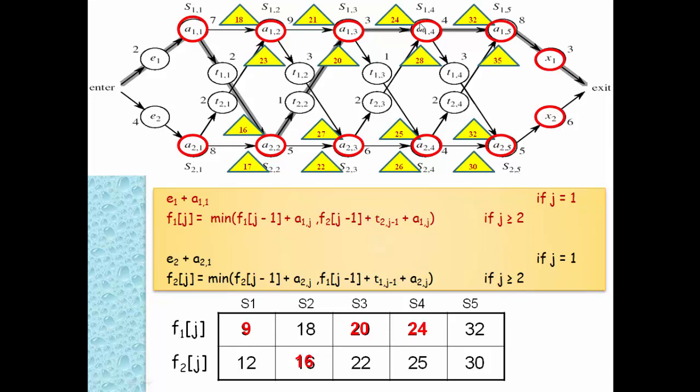So for example, we are on station number 4 here, and our minimum time required by the station was 24 in this case. At that time either we can move here or we can move here. When we move here, compulsorily we have to choose the X1 gate. When we move here, compulsorily we have to choose the X2 gate. So let us check both possibilities, and we have to choose either A15 or A25. When we move from A14 to A15, it required 32 units of time. So 32 plus 3, that is 35. So our answer will be 35 to make one car.